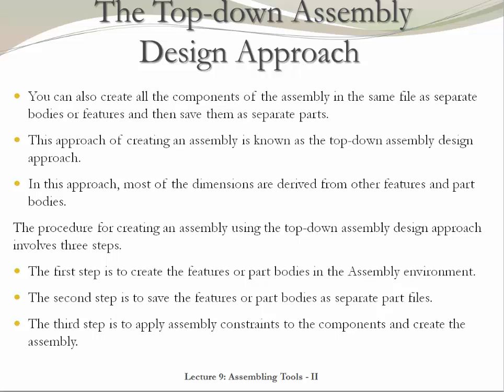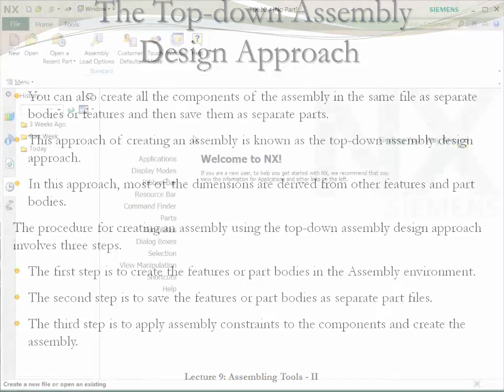Let's start with a description of the top-down assembly design approach. In this approach, the user has the ability to create components in the assembly environment. Each of these components will be saved with its own file name. The advantage of this approach is that the user has the ability of using the dimensions of the components that are previously used. This is very useful when the objects have very complex curvatures and dimensions.